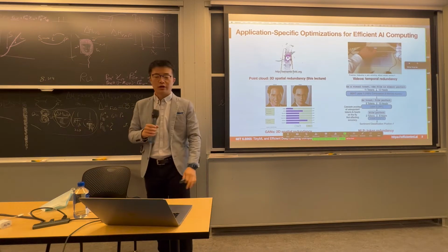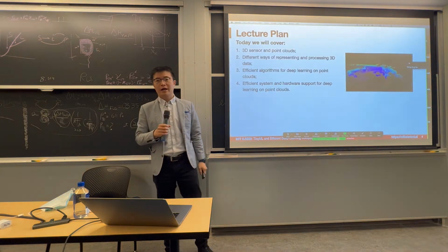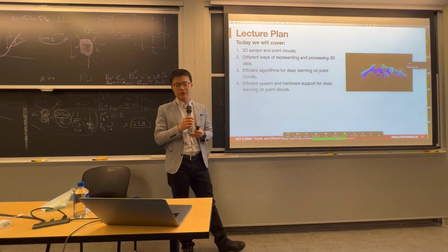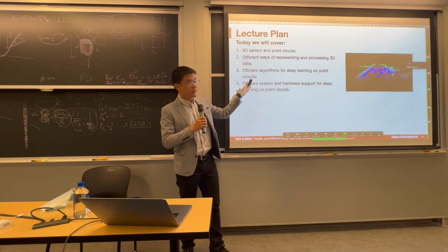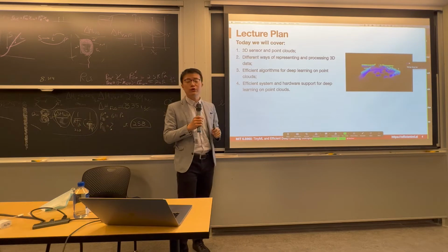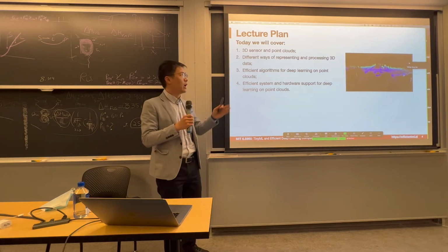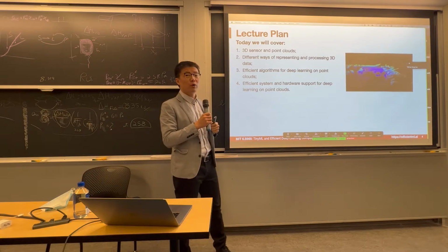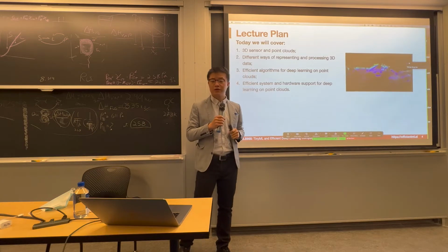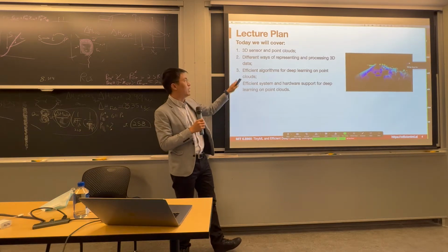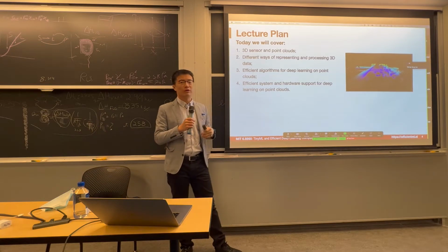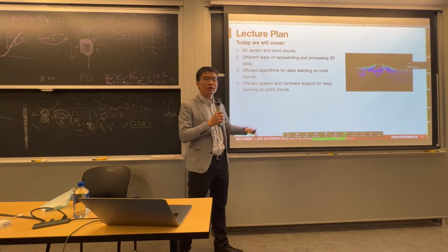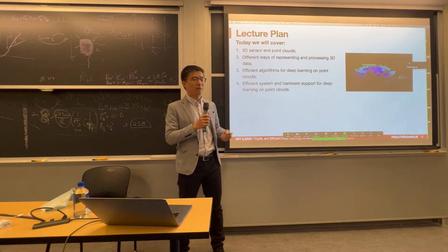So today, let's start with the first topic to talk about LiDARs, okay? 3D temporal spatial redundancy. How do we remove those redundancies? So this is the agenda for today. We are going to first introduce the 3D sensors and how the point cloud is generated by 3D sensors, followed by different ways of representing and processing 3D data, followed by efficient algorithms for deep learning on point cloud, and also efficient systems to implement and to support such efficient algorithms for point cloud.